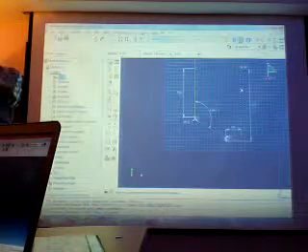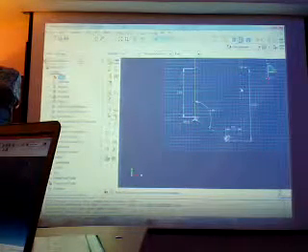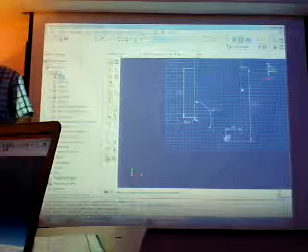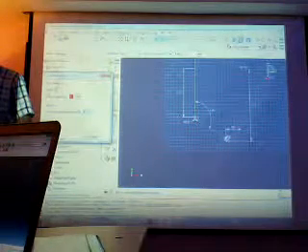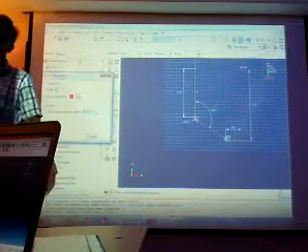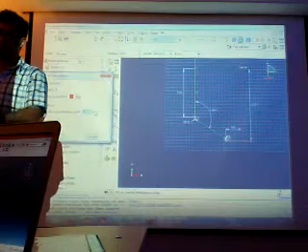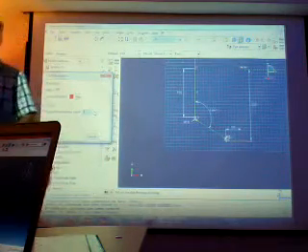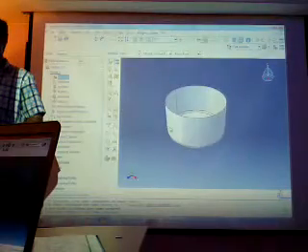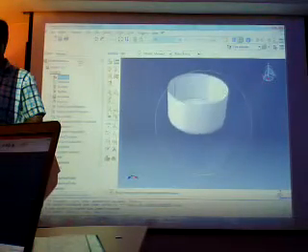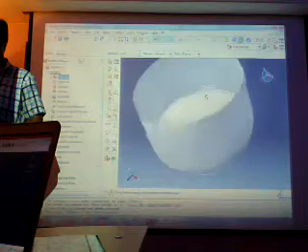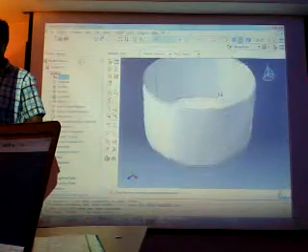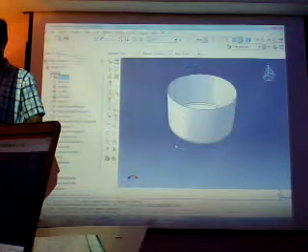I should take a center line because I take another axis. Now it's necessary to take the center line. This one, the angle of the rotation is 90. We should change it to 360. Okay, now we have our die. You can see the die here. As you can see, we have just the shape.